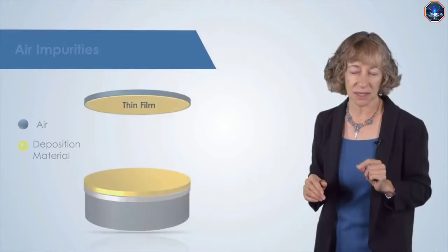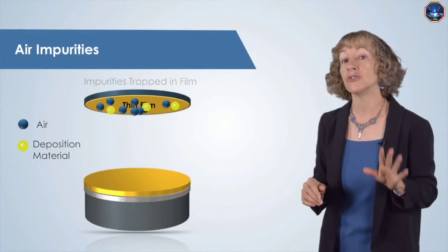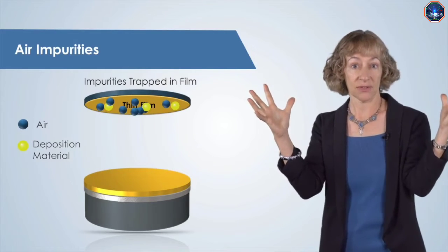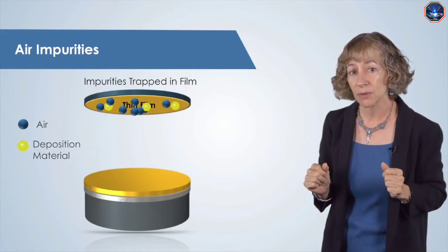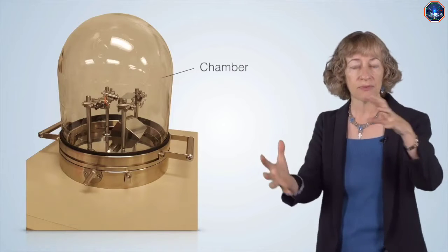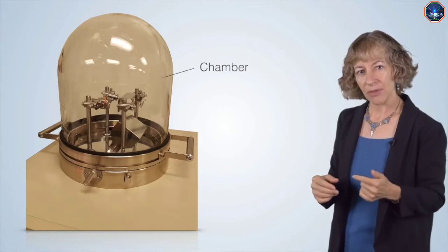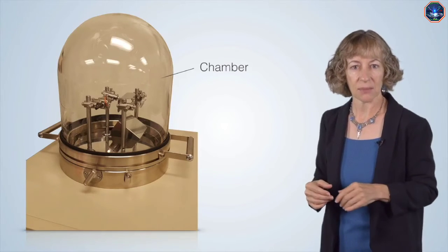But a clean room alone is not sufficient for our thin films. Most of these nanofabrication techniques are extremely sensitive to any impurities and contaminants, which also decrease yield. These processes are so sensitive, in fact, that the air itself could result in defects that affect the purity of our thin film coatings. So this leads to another requirement for depositing thin layers of high purity materials. We deposit the materials in a vacuum system. A vacuum system is any piece of equipment that has a chamber that provides an environment which is nearly free of all air molecules. Now let's talk about the processes that we use for fabrication in these clean environments.